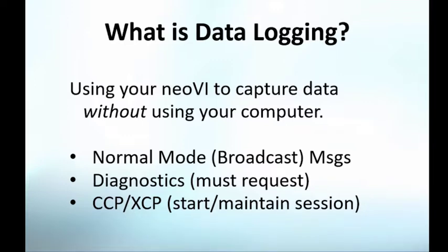So we have normal mode messaging, which is normal functions of the car, diagnostic messages, and CCP and XCP. With diagnostics and CCP, XCP, you have to build configurations to obtain those messages. Those aren't normally broadcast on the car. So we have tools built into the software that make this easy for you.